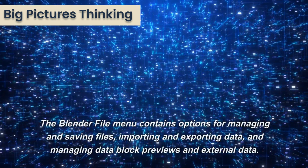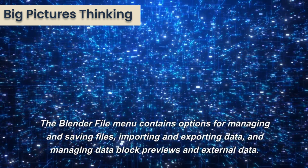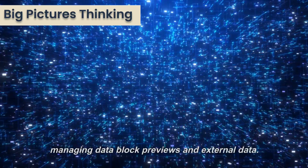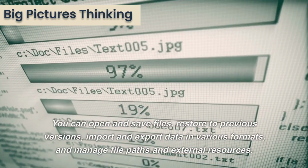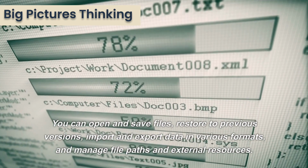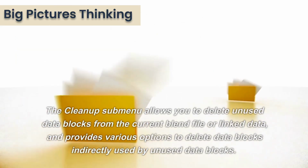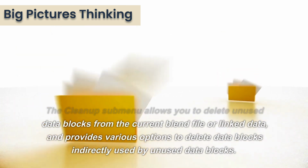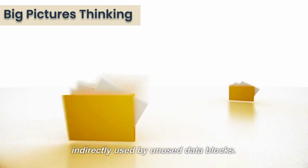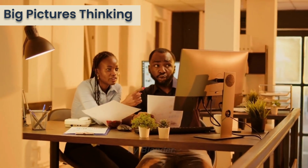The Blender file menu contains options for managing and saving files, importing and exporting data, and managing data block previews and external data. You can open and save files, restore to previous versions, import and export data in various formats, and manage file paths and external resources. The Cleanup submenu allows you to delete unused data blocks from the current blend file or linked data, and provides various options to delete data blocks indirectly used by unused data blocks. The default submenu manages the startup files used by Blender.